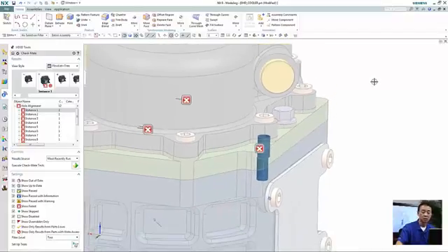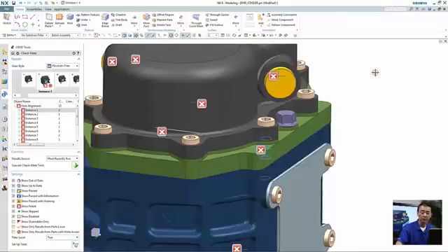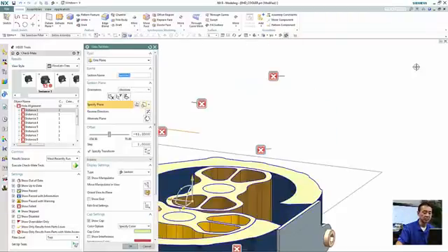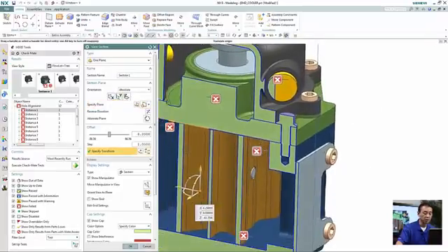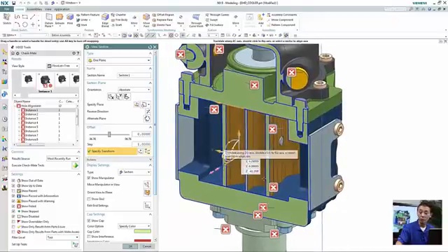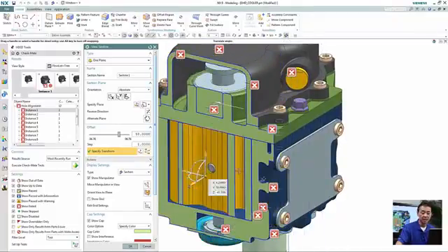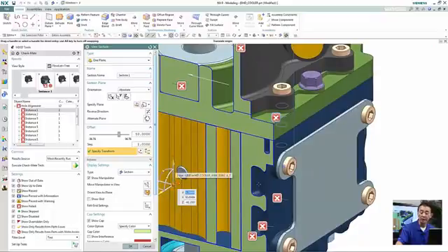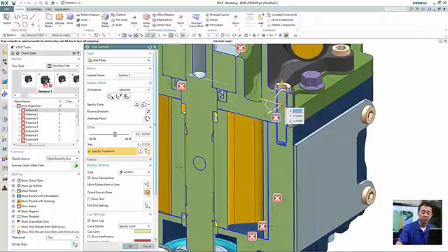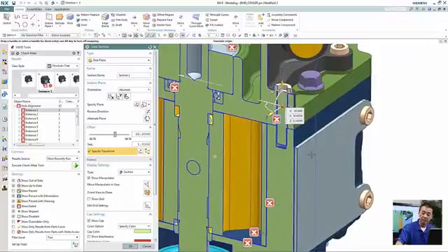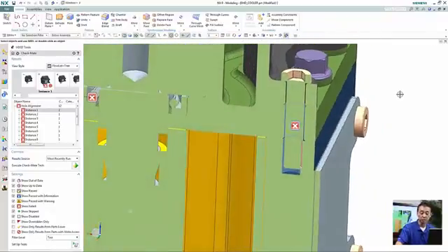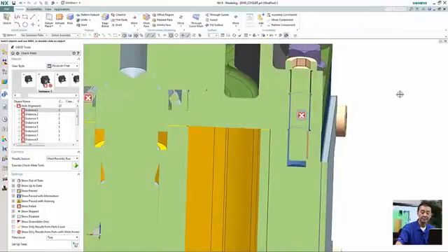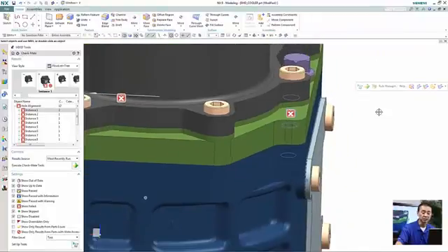So let's take a look using a section view, to see if we can get a better look at what that looks like. Let's go ahead and execute this particular section view. We want to see that in a particular direction, and using the manipulator we can quickly move through our design and then stop at a particular hole location where we believe there are alignment problems. Once again, we can get a feel for what kind of misalignment. This is the type of quick result that we can see from design for manufacturing for the assembly.